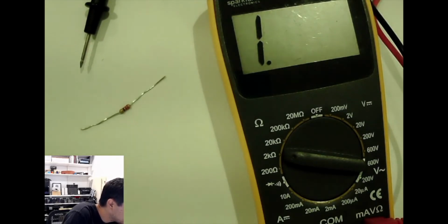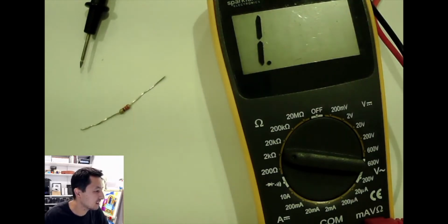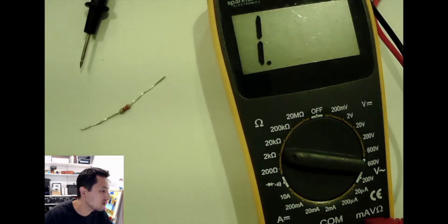Does it have the icon with the V and the straight line and the dots? Yeah, it does. Okay, so I would try that. Just turn it to get a 9-volt battery. Turn it to the 20-volt option or within that range, anything above 9 volts that's not too huge a value, and then test it to see if you get the value from that.